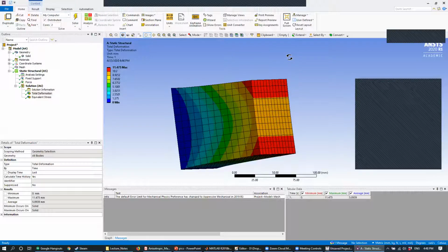All right, question. Do most engineers who work with wood a lot usually depend on tabulated data? That's tricky. I know with wood, a lot of it depends on the moisture content within the wood too. There have been a lot of studies on how wood behaves and a lot of tabulated data, but a lot of it depends on things like the moisture content.